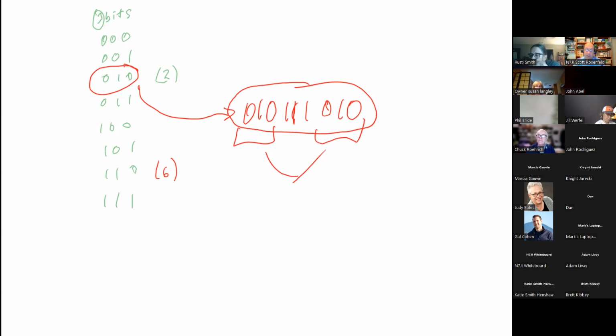And if anyone's curious, if they have a radio, wherever you are, you can go to 144.390, and very often you'll just hear packet bursts being sent automatically. APRS is a packet burst over FM radio. Did everybody hear that? Yeah. That annoying sound? Yeah. Okay, that's packet. Instead of voice, it's basically data over your FM radio. Automated packet reporting system, that packet was probably an APRS packet burst.